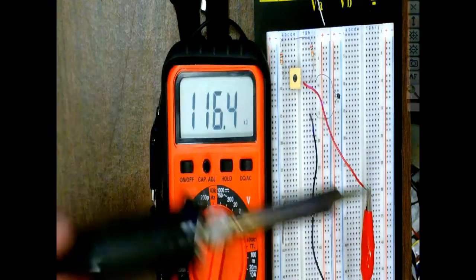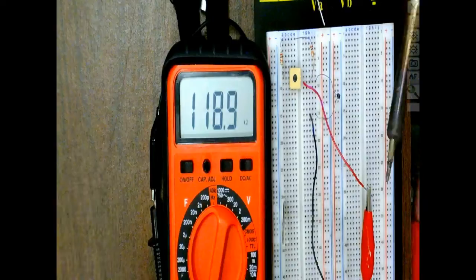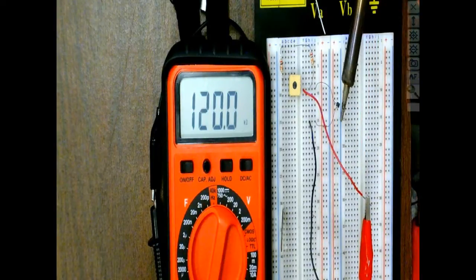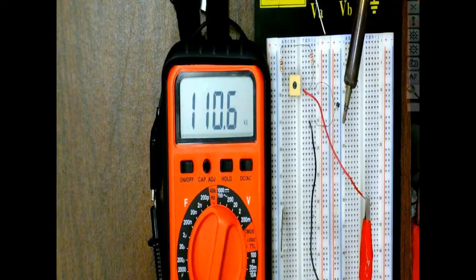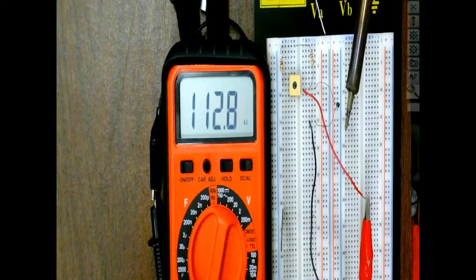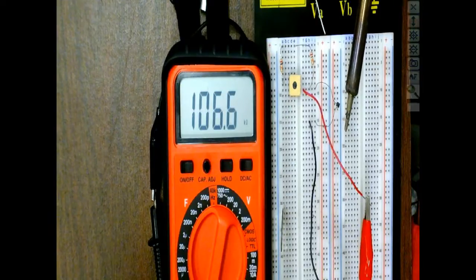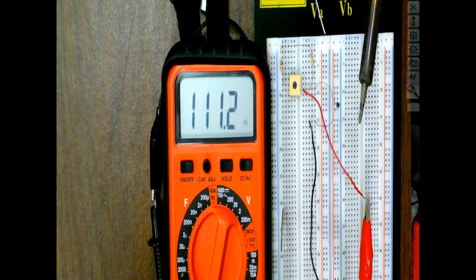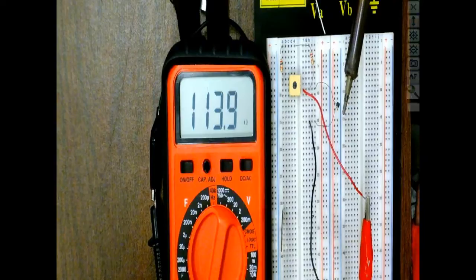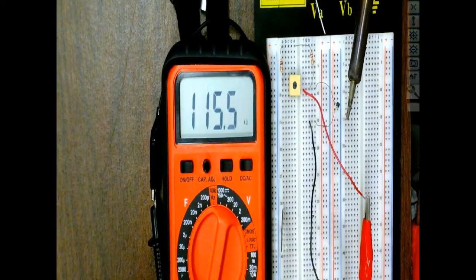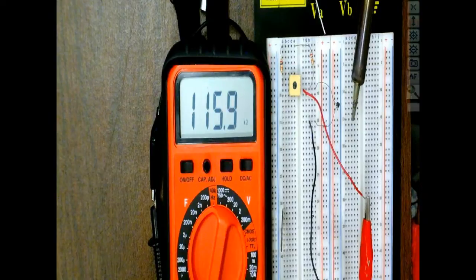Now, of course, this right here is a sure enough heat source. This is a soldering iron that I've got plugged in. And you can see the resistance starts going down. And I'm not touching this, guys. I'll put it off to the side so y'all can see. Eventually it would come up here and stop, depending on the temperature of the soldering iron. And by the way, we have soldering irons that you can control the temperature of. Well, how do they know the temperature? They use a thermistor that's actually in the head of the heating element, that we can use to control this.